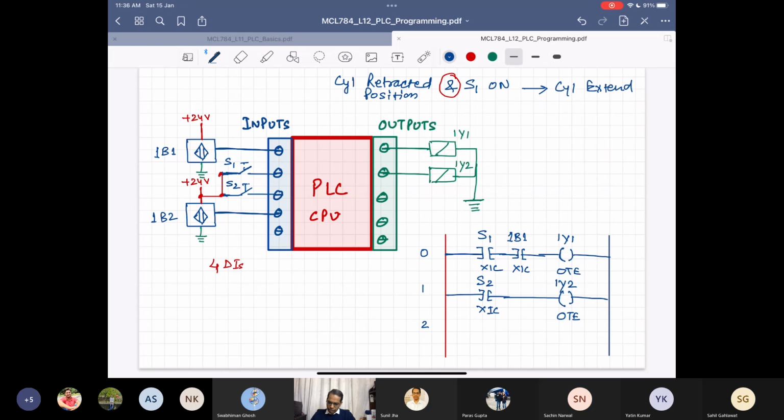Yeah, so first let us discuss the changes that we need to make on the electrical circuit diagram or the connection diagram. Sir, the second output we can remove. Yes, so this is not there. So we are only having one solenoid here. We still require two push buttons. Yes. Okay. And we will be having two proximity switches to sense that. So that remains fine. So we'll just use one output solenoid. And now you are seeing some changes on the ladder logic. What should be that change?